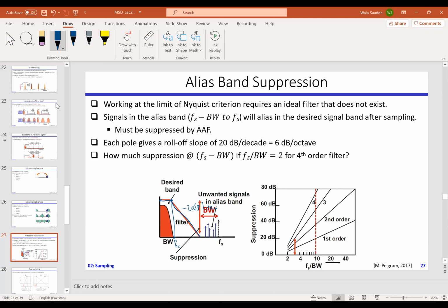In reality, at this FC, we have an amplitude that is minus 3 dB from the maximum value. If I have, let's say here, 0 dB, at the FC each pole will cause it to be minus 3 dB from that original value. And we discussed that in the microelectronic design, as far as I remember.